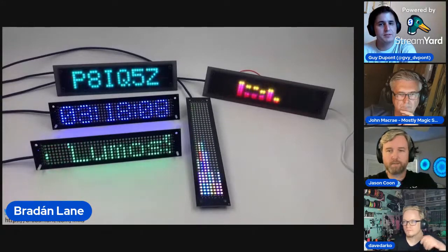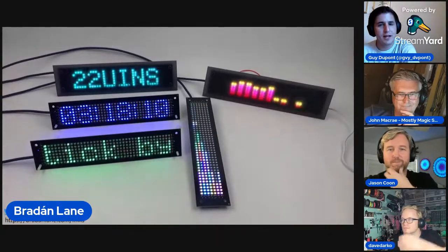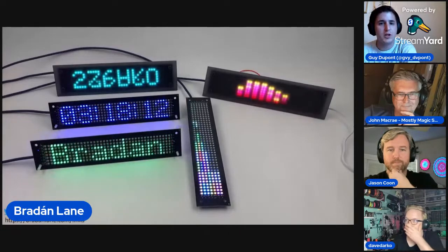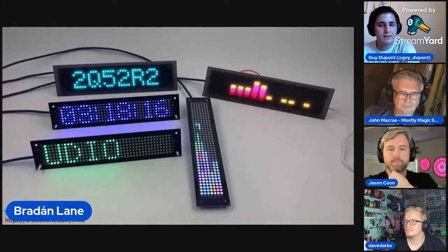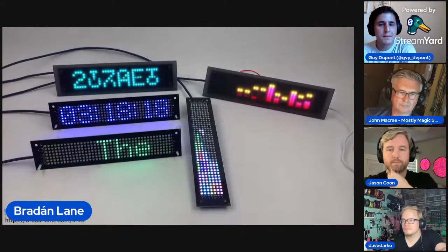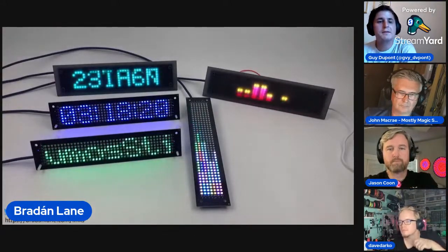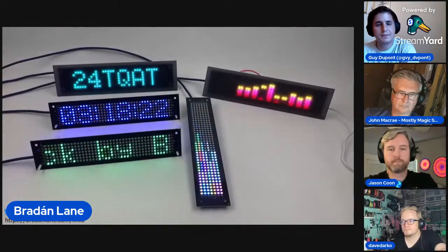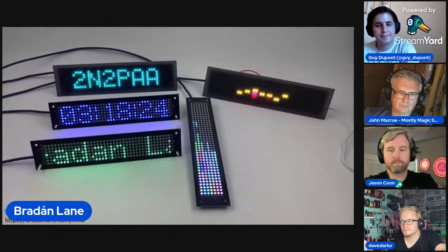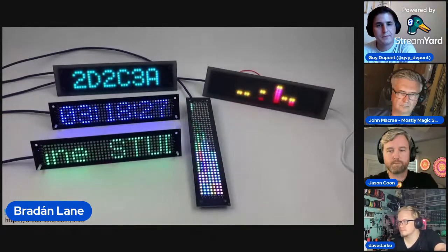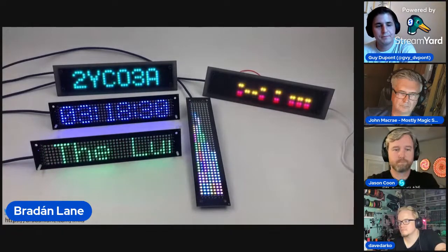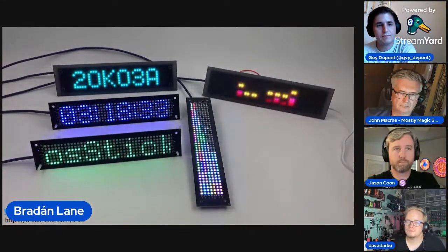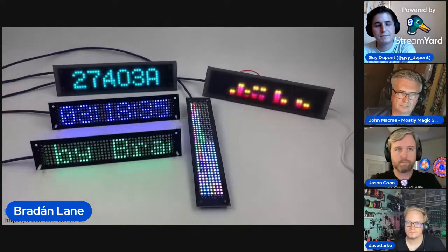That was going to be my question. You said that there's an amp involved, so you have audio on board. I missed that. It's so that people who are building projects can do things like beeping and alarms. When I did the Lumis Ring, I put a single mono amp off the GPIO pin to the little speaker buzzer to boost the volume.